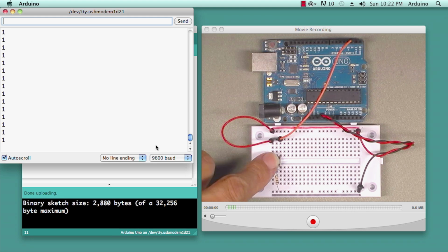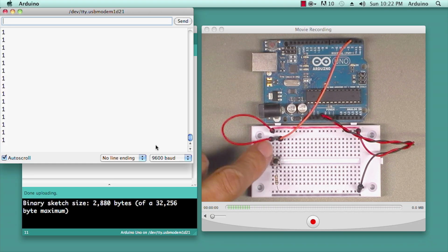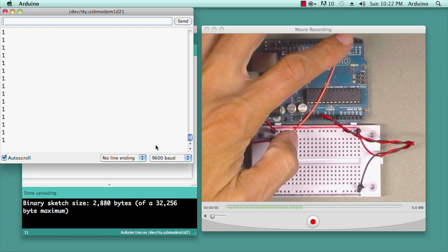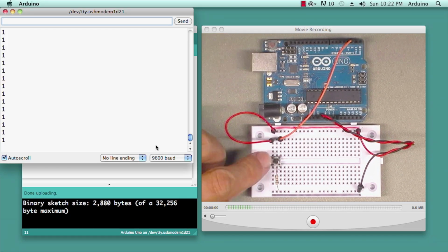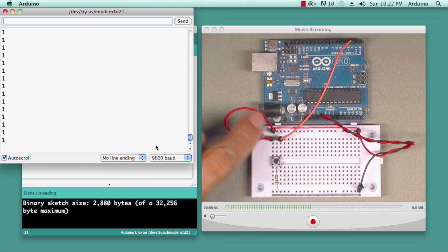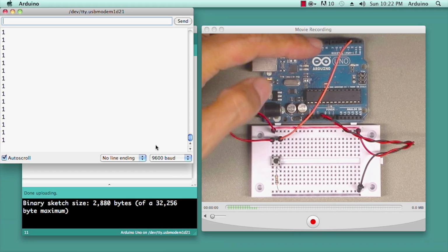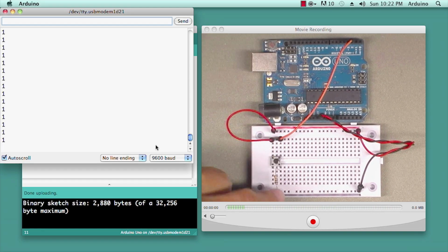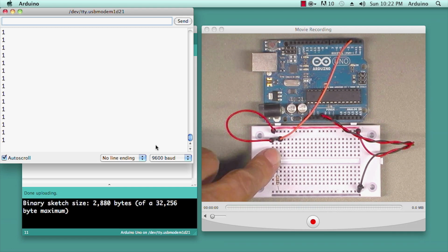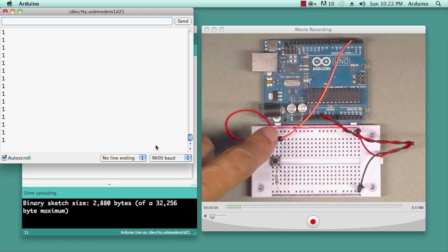When we press the button, the path of least resistance: here we have a huge resistor, and here we have just a switch going across through a wire. There's no resistance here whatsoever. That path is going to be wire into the switch, and when it's pushed across the switch, up this column to the red wire to 5 volts. So you can think of it from the standpoint of the input. The input either sees 0, because we go through the right-hand path to ground, or if we push the button, it goes through the left-hand path to 5 volts.